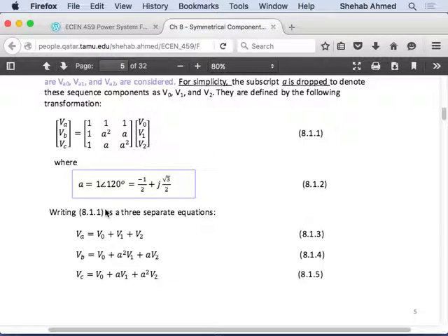It just comes from the fact that we agreed that if a voltage is unbalanced, it will contain zero, positive and negative sequence components, and the full voltage is equal to the sum of them for each of the phases. We represented that using these phase shifts, and we took that and represented it as a matrix. We will call this the sequence matrix. Yes? So you're representing VA, VB, and VC in terms of the zero sequence, positive sequence, and negative sequence components of phase A, of one phase.